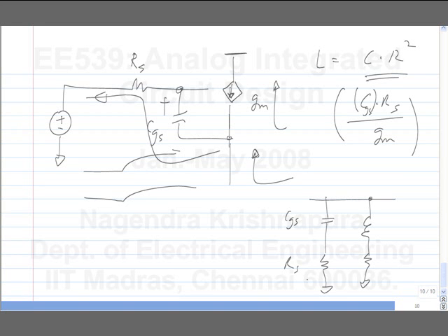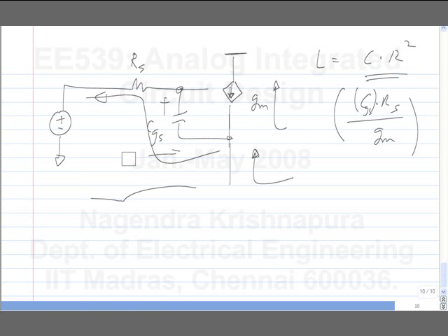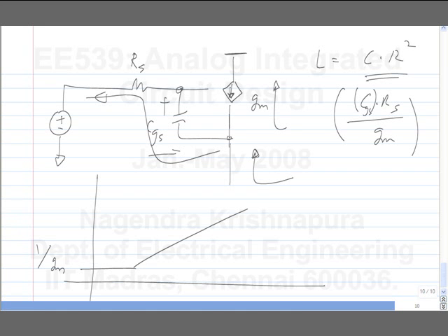Why is this not a second order system? So the time constant of this branch happens to be exactly equal to the time constant of this branch. So that's true. The inductor description holds only for the current that is flowing through Gm. Anyway, we evaluated the output impedance and said that it goes from 1 by Gm to Rs. Now we ignored this parasitic capacitance, Cgd.